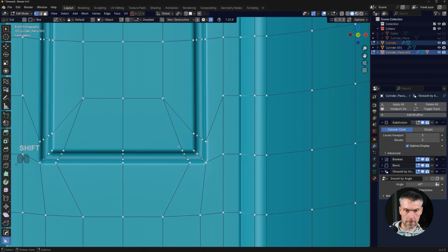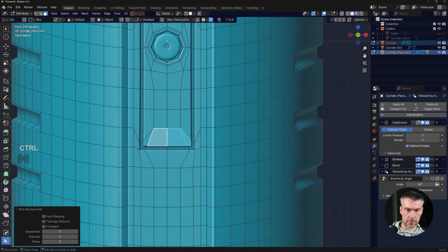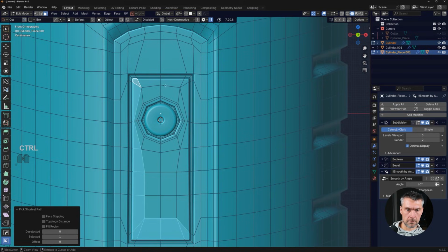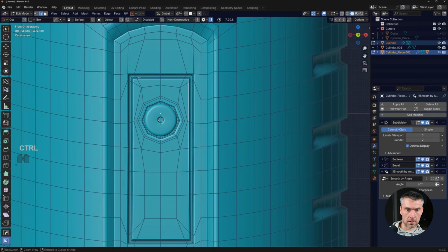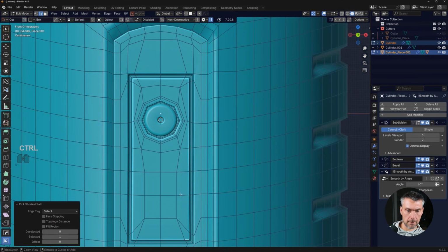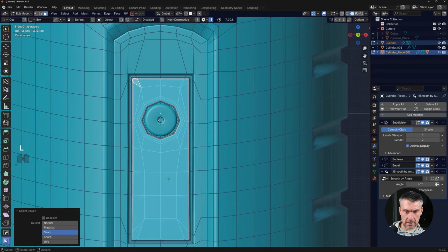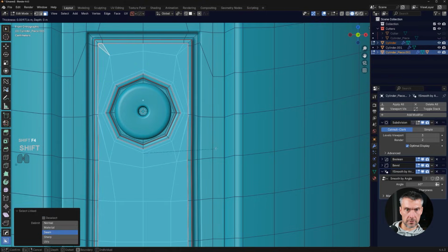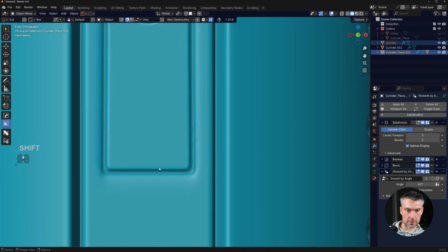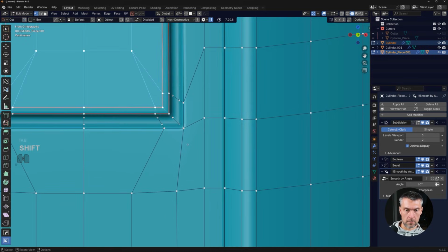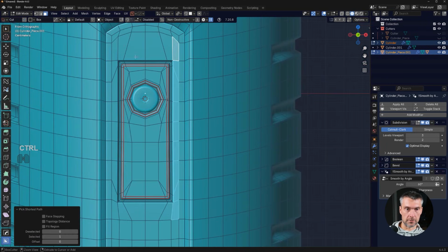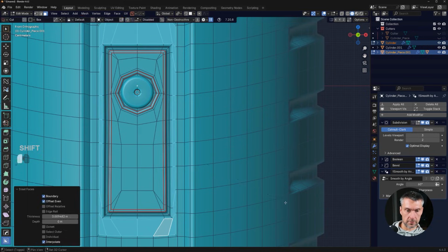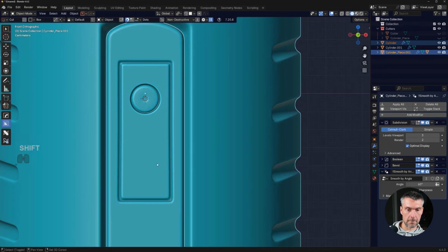So let's grab this entire shape here in the middle. In fact, what we could do is select this one and this one all around, mark them as seam, press L here in the middle, and just simply insert this, right, like this. Okay, it's going to tighten this entire structure, you see. And here, well, we probably would need another loop, right? So what we could do here is select all this and then just insert it like this, and you're gonna get a perfect square here.